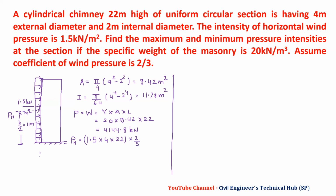And then M is PH into H by 2, the moment about the base. H by 2 is 11. So we have PH 1.5 into 4 into 22 into 2 by 3, and that is into 11, which is H by 2. And we have M as 968 kilonewton meter.